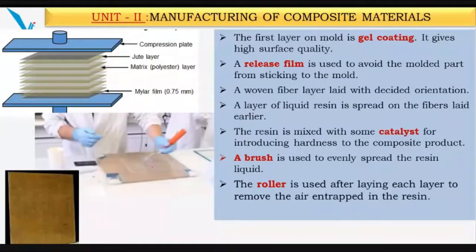Once you apply one layer over another, you can put this under a simple mechanical press or compression molding, so that it will take that particular thickness. You can even provide spacers here to achieve uniform thickness. For natural fiber based fabrics, you need to use this compression molding, which is supported with the hand layup process. So these things I explained. This is a particular jute laminate.